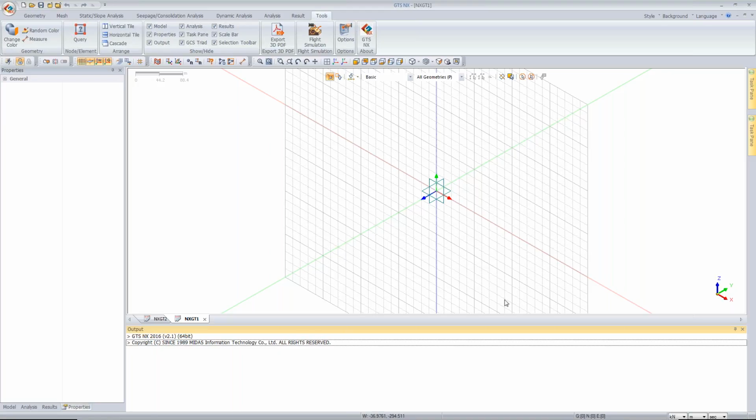Now, as you can see on the right-hand side corner of the working window, the program shows you the GCS, or the global coordinate system, which is X, Y and Z in the vertical direction. Then you have the work plane where you can see the grid. It's very important to understand that any 2D command which you will be creating will go in this work plane.